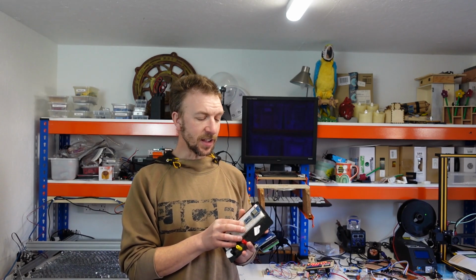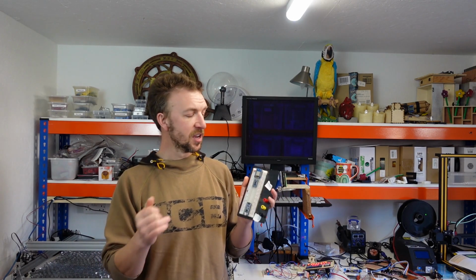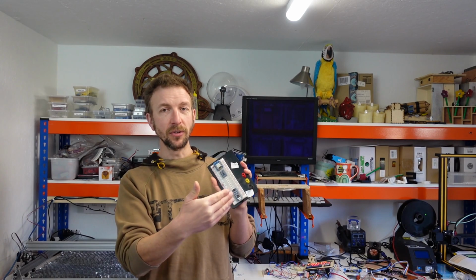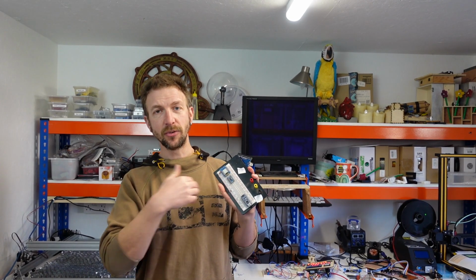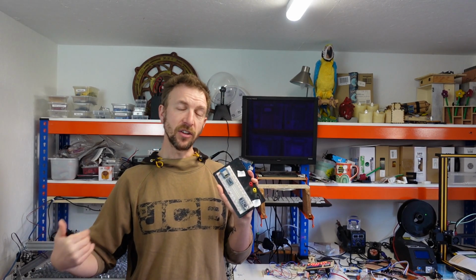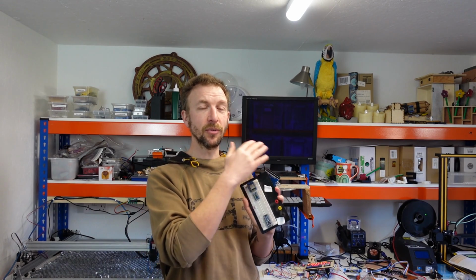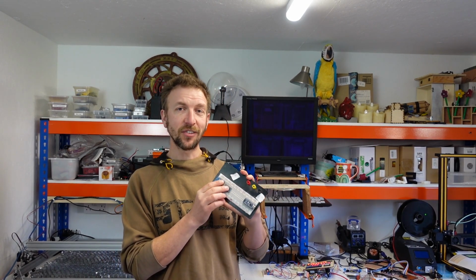The idea here is that the bus is running at a certain voltage, so let's say it's a 5 volt bus, but every time you have a 3.3 volt device you want to connect to that bus, you put one of these logic level converters in between the signals, and it will feed a high signal on one side into a high signal on the other side, and likewise it's bidirectional, so a low signal on this side will translate to a low signal on this side. And I thought, well, that's great, I've got a load of these logic level converters, so let's slap those in.